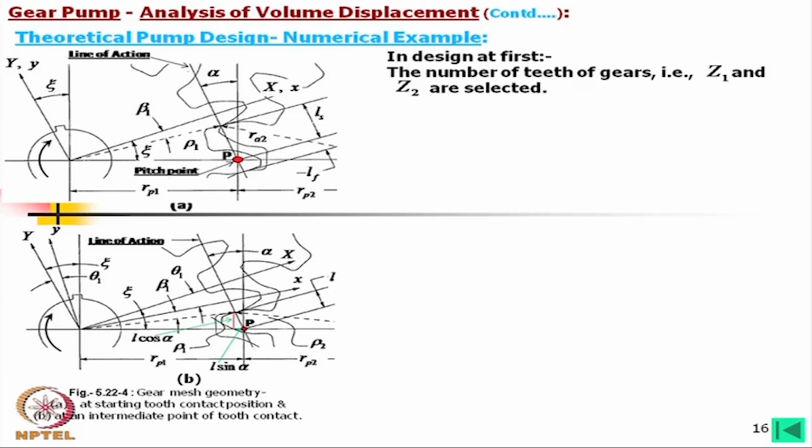If we select the 20 degree pressure angle, in that case we will probably take Z 1 and Z 2 very close to 17, which is the minimum teeth number for 20 degree pressure angle, and probably we will compromise from 20 to this side, maybe 16, not less than that. 16 teeth without gear correction is possible if we use a suitable pinion cutter. So, in that case we may consider from 16 to 20. Let us consider, say, 16. So, 16 for Z 1, and Z 2 is also 16.